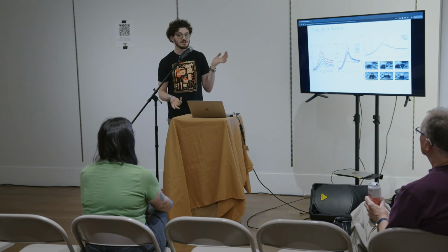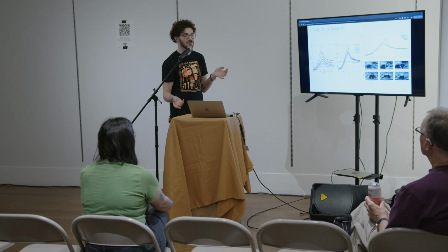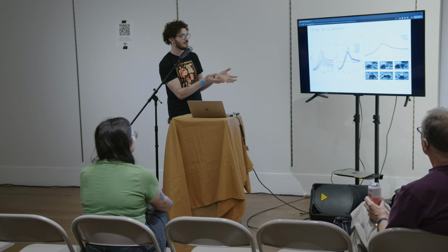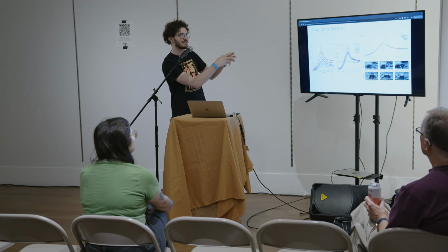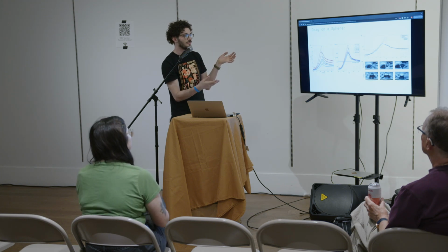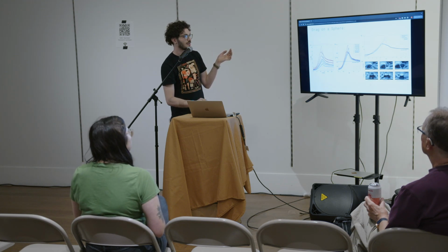This is something that wasn't documented or observed, and so this paper showed this and also showed how whether the sphere is wetted or not matters a lot. The shape of the drag and how much drag you experience is different going into the water when the sphere is dry versus coming out while it's wet. And then it's also strongly dependent on the surface.